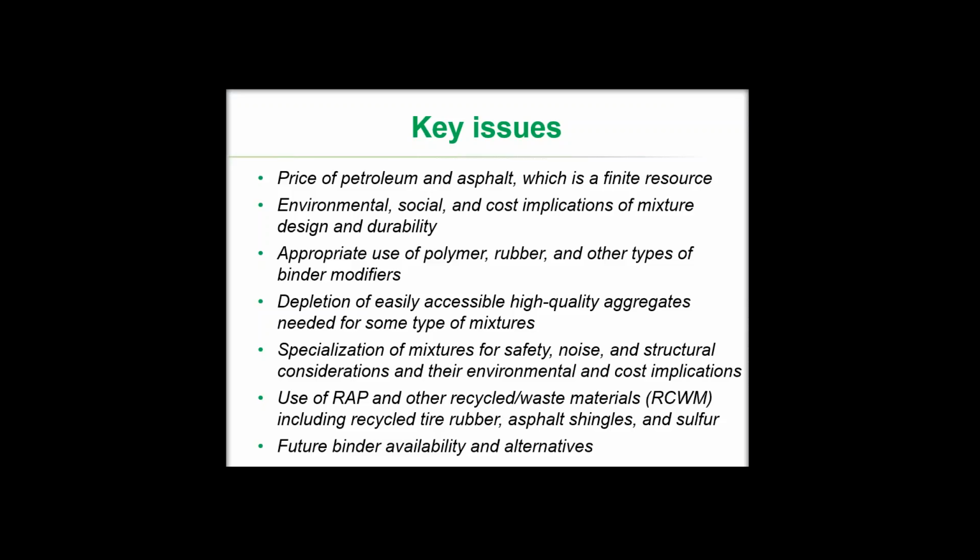Specialization in mixtures, the right material in the right place in the pavement at the right time for safety, noise, and structural considerations, and then balancing those with the environmental and cost implications. Rapidly increasing use of recycled asphalt pavement and other recycled and waste materials, including recycled tire rubber, asphalt shingles, and sulfur, and future binder availability and alternatives.